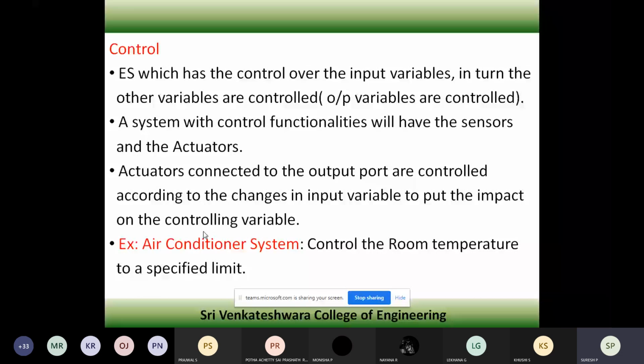So depending upon what it is going to control, depending upon the impact of pressure. Whether the airbag in your car has to open or not, that you should know. That depends upon the input variable. Here the input variable is nothing but your impact, which is being sensed. The pressure sensor will sense with what pressure the impact has happened, and depending upon the pressure of impact, the actuator has to perform the operation of opening the airbag.